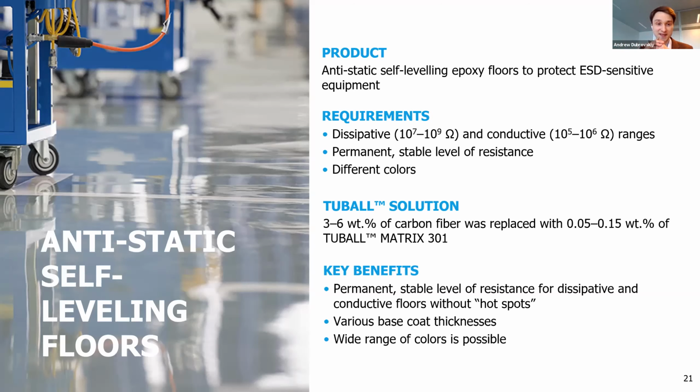And finally, we came to a conclusion, and we observed that the servicing company did not check properly the electrical conductivity of the primer. And of course, the primer was in between the top coating and the copper tape, and that's why there was no surface to ground resistance. But our customer was extremely happy that they were able to provide surface to surface conductivity.